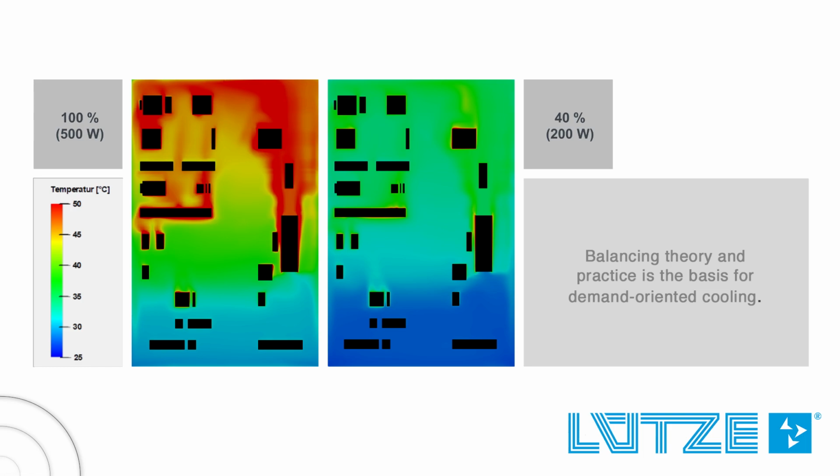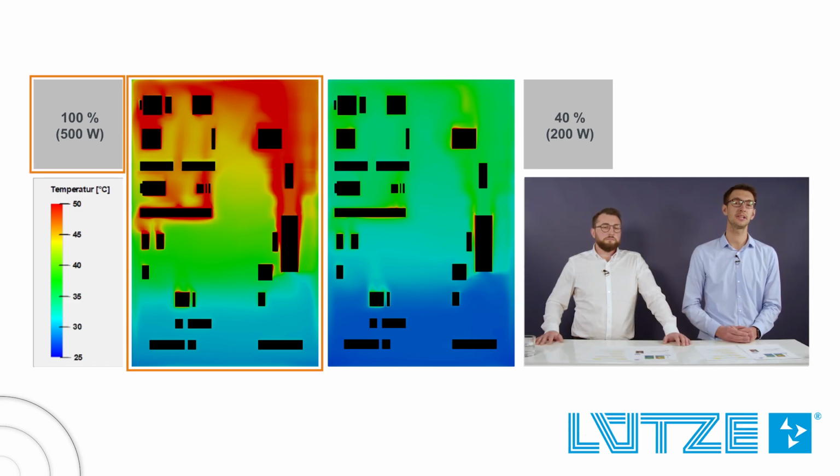It's essential to know where each component is positioned within the space. And the most critical factor is the system's load, which is the power loss it generates. For reference, I have an illustration. It shows two diagrams, cross-sections of our flow simulation. On the left, you see the simulation with 100% potential power loss, which simply sums up manufacturer-provided power loss data.